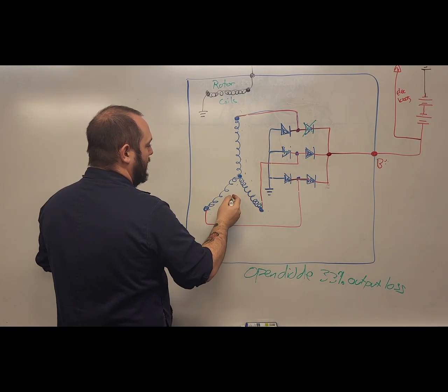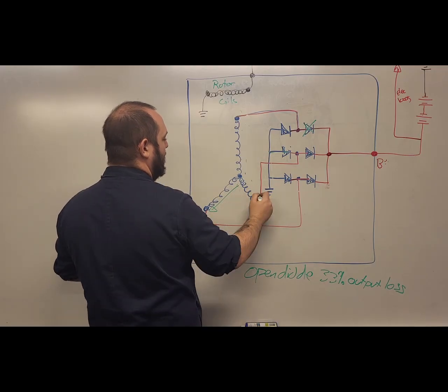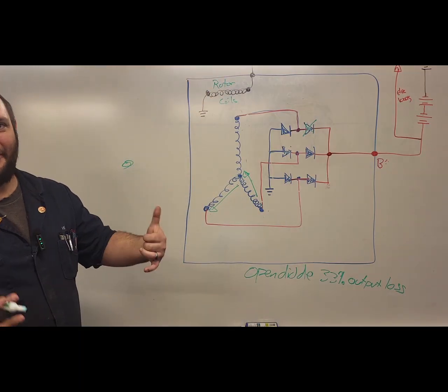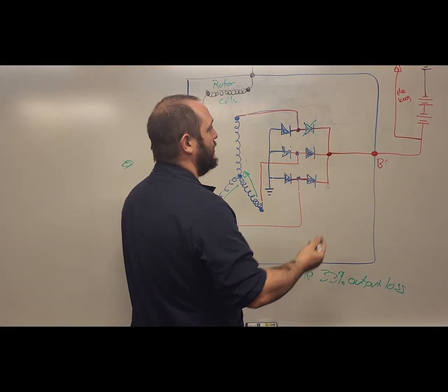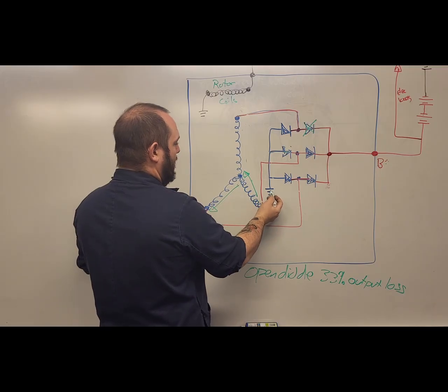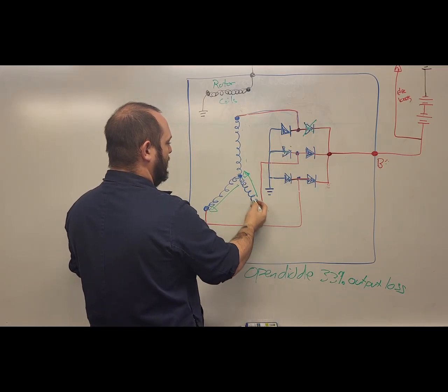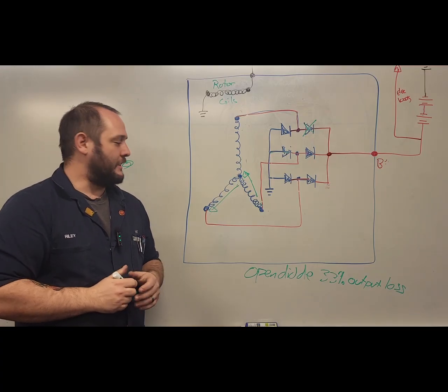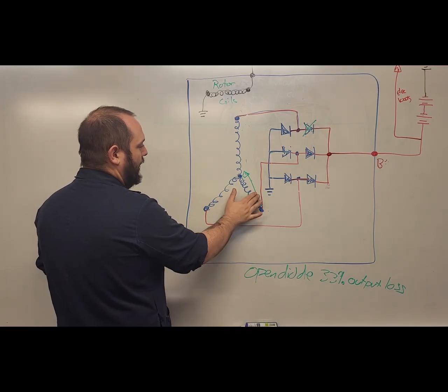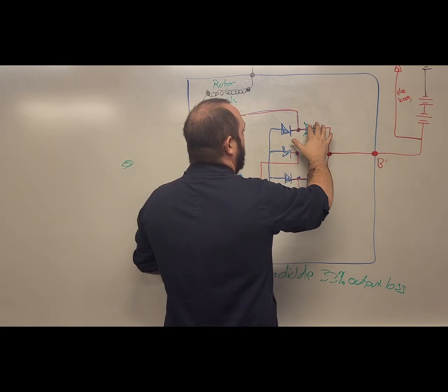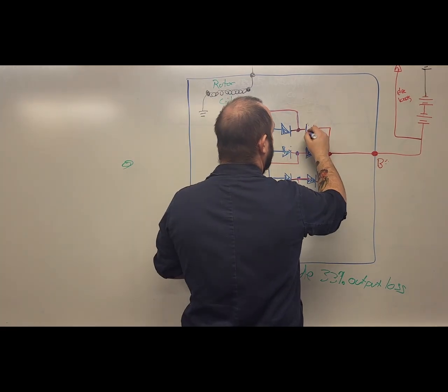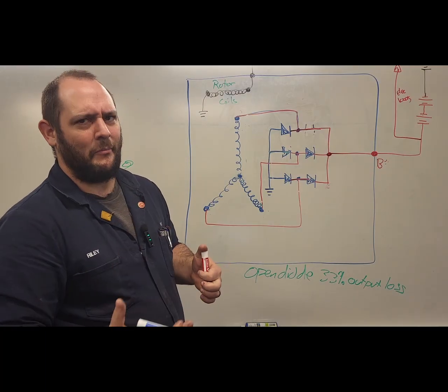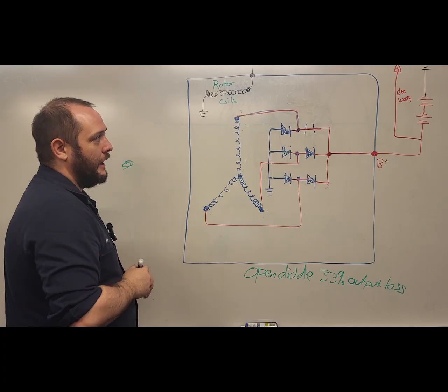Now, if we go out on this leg and return on this leg, that current will flow out, go to my electrical loads, run my electrical loads, charge my batteries, do whatever it needs to do. It'll return through my ground circuit, and it'll be able to flow back in. An open diode will yield us a 33% loss. Now, if I change this up and we look at how the current behaves through a shorted diode condition, it can go through in either direction. It doesn't matter to me. That diode is essentially not in place, and I have just continuity through that conductor.